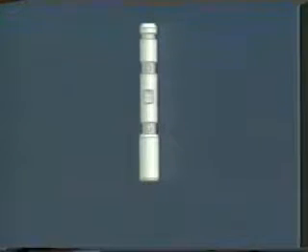A cutter bar consists of a wireline socket attached to the top, one or more lengths of stem, and a blind box attached to the bottom. It is used to cut the wire at the top of the wireline socket of a tool string that cannot be retrieved from the well. In such an instance, the cutter bar can be dropped into the well bore where it will bypass the wire line and fall to the stuck tool string. The blind box on the cutter bar bends the wire over and mashes it against the wireline socket of the stuck tools, thereby cutting it and allowing the operator to retrieve the maximum length of wire line.